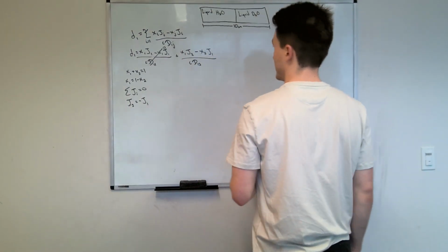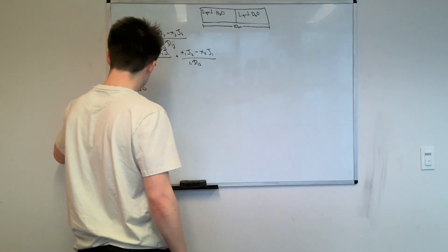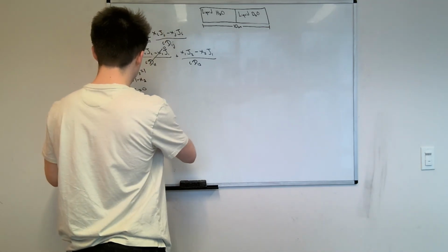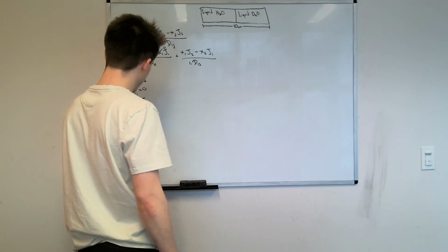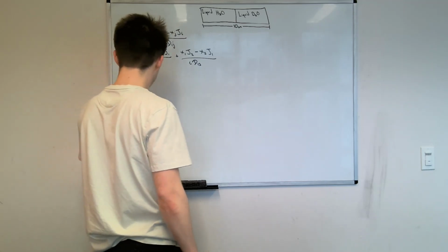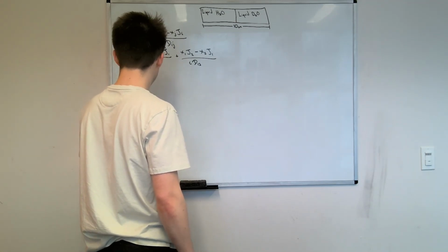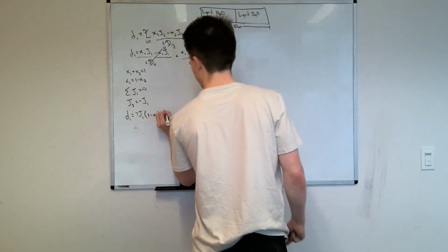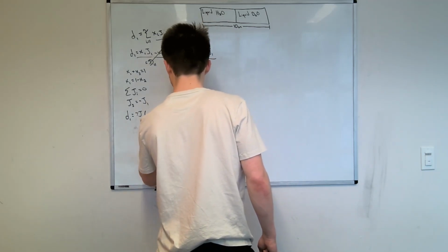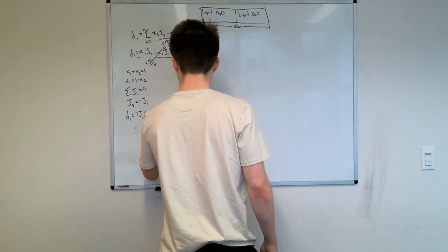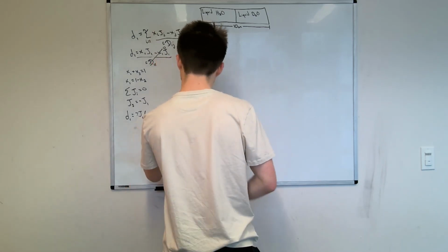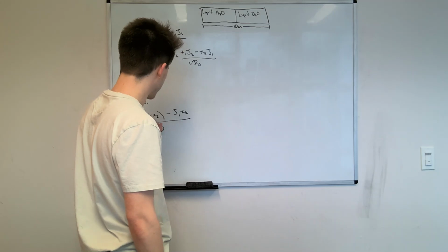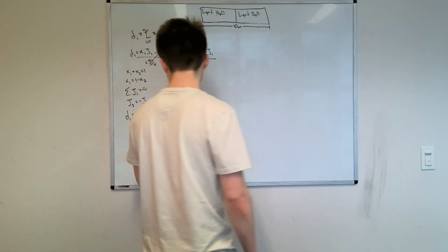So plugging in that information, we get the driving force is equal to negative molar diffusive flux of 1 multiplied by 1 minus x2, minus molar diffusive flux of 1 times x2, over concentration times the Stefan-Maxwell diffusivity.